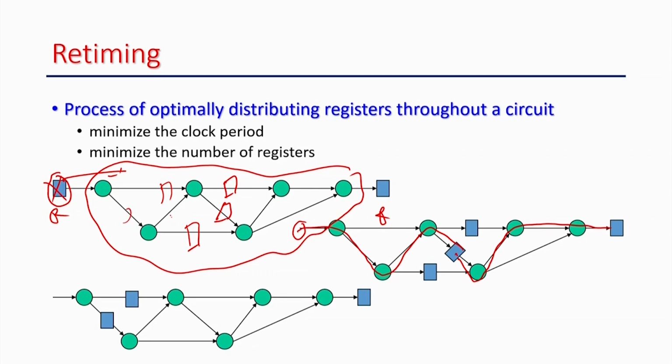So, this is the core concept of retiming, and you can understand that given a bigger circuit, you have a lot of options, a lot of possibilities of moving registers. This circuit is not like you have 8 or 10 gates or only 2 registers. Your circuit may have say 10,000, 20,000 registers, a million gates, and maybe more than that also. So doing these things physically or manually is not possible. So, we have to automate this process.